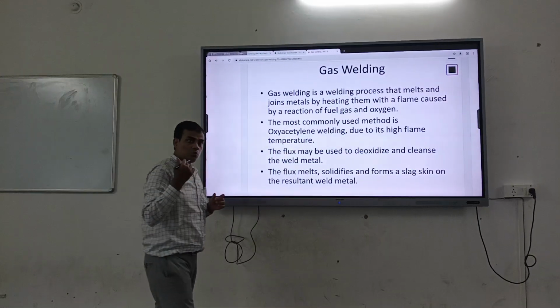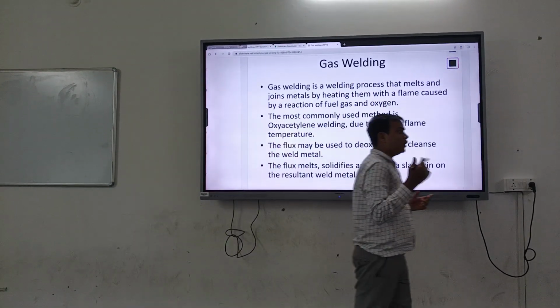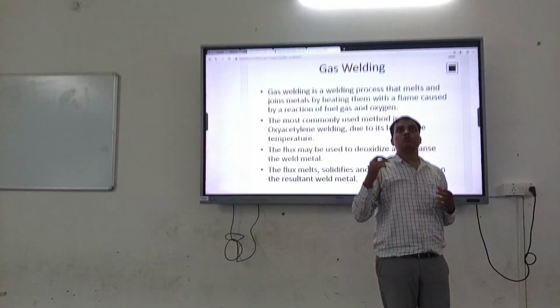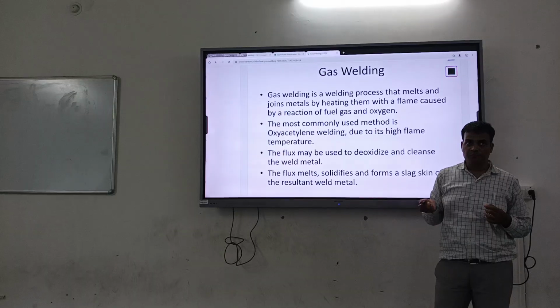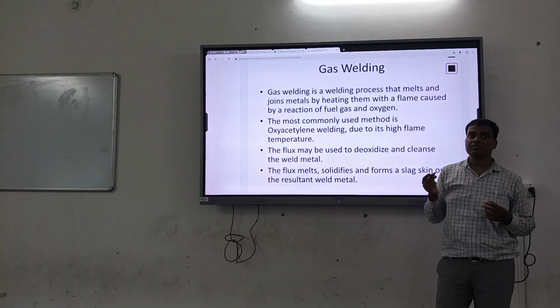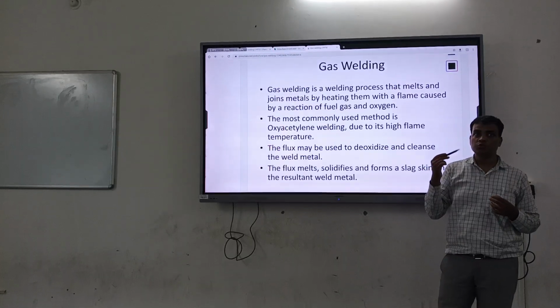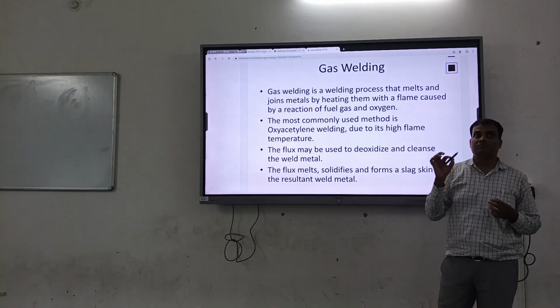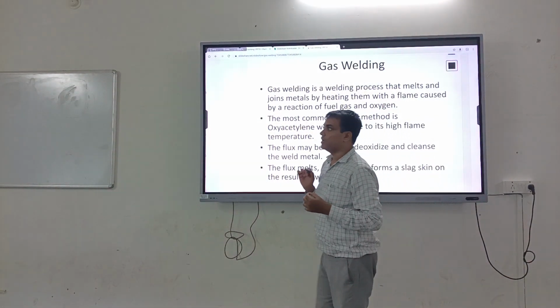So we first have to understand which type of material I am going to join. First of all, we should measure the thickness of the plate or workpiece. Otherwise, it will not provide an appropriate joint and appropriate strength because of the heat.